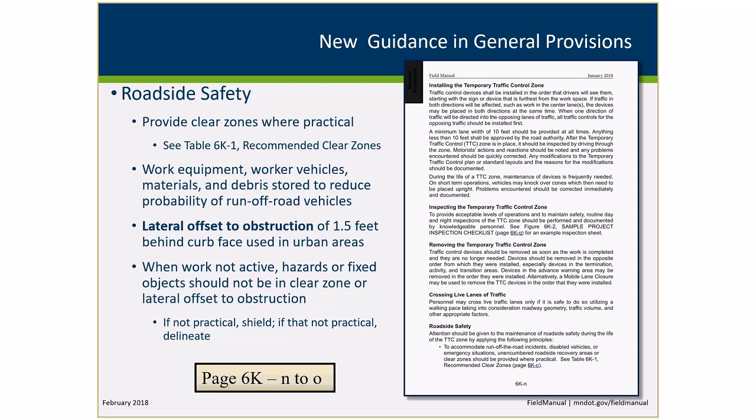If it's not practical to shield it, so if you've got a crane out there and that's the only place that you can store it, and you're only out there for a day or two and it's not practical to have a traffic control operation to put out barrier, then you can do something else. If it's not practical to shield it, then you can delineate it.